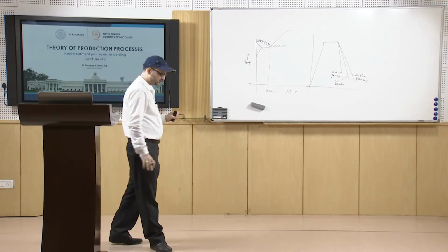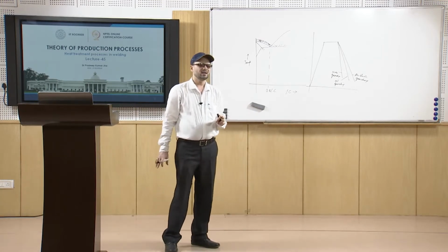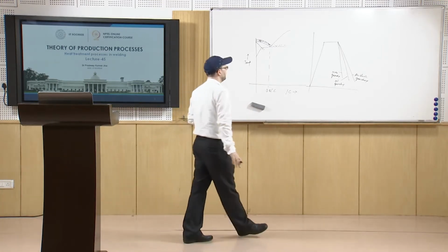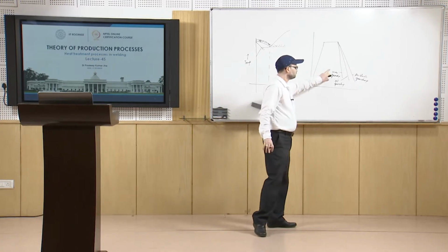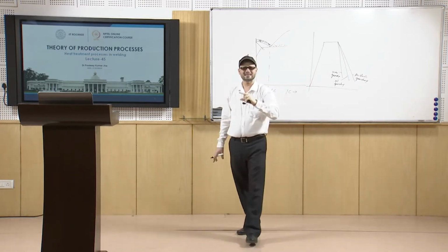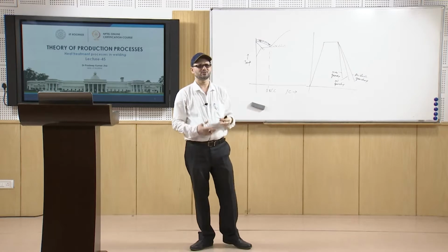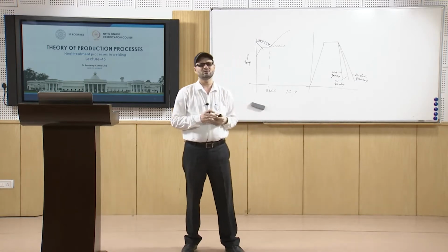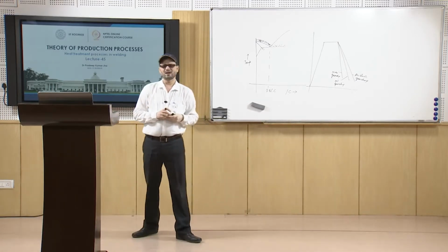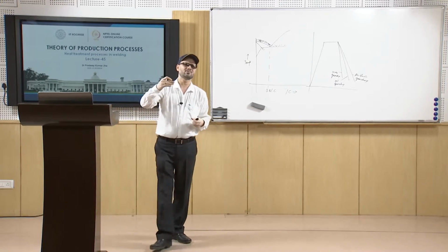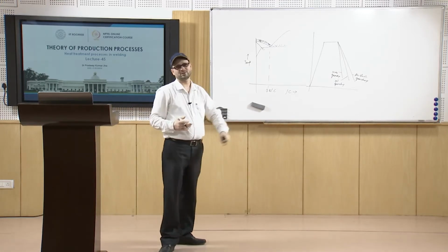Now, in the case of quenching, one thing to be understood is that when the carbon percentage is less than a certain value, like 0.15% or so, there is not much effect of quench hardening. It is also not advisable when the carbon percentage goes above 0.8%.